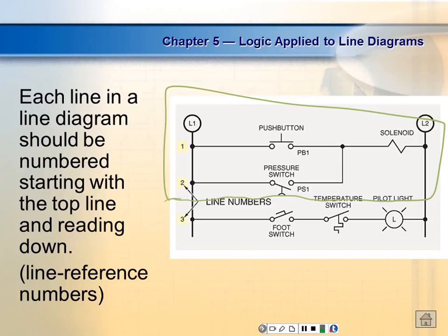And they do it a little different because with these line diagrams, you can't fit the whole diagram on one page. So they split this whole ladder diagram up into pages. So what they do is they start off with a page number like 138-1. Okay, so the 138 would be what? The line number would be the page number that you're on, and then the 1 would still be the line number. That is basically exactly the same. Everybody okay?